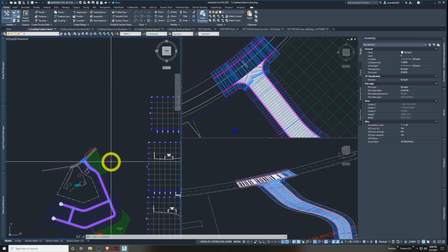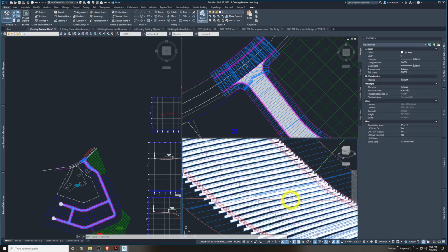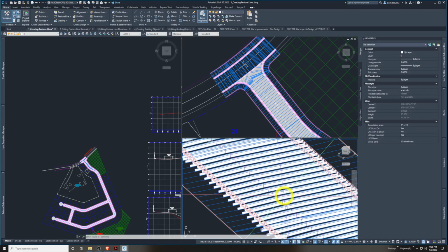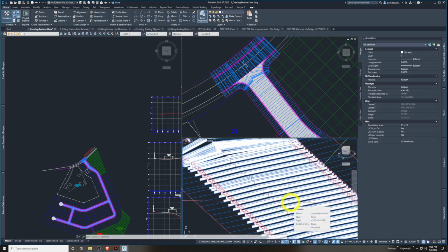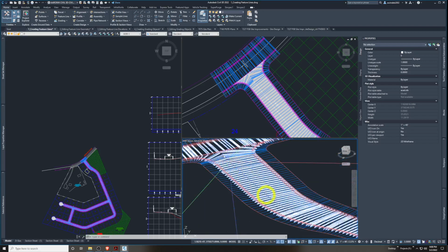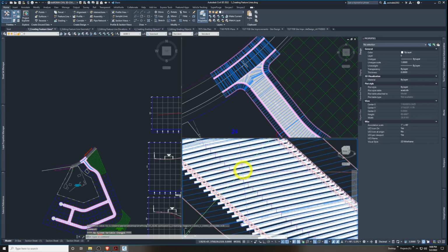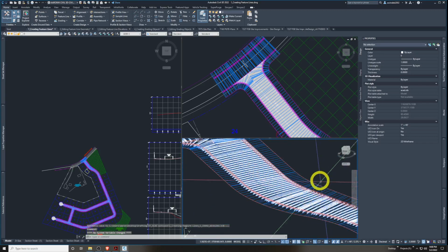Whereas when we learned earlier, and also tying back to Chapter 9 in corridors, we got cross sections and assemblies. So basically, to start over again, we had alignments, which set the horizontal more or less. We had profiles, which set the vertical more or less. And we had our assemblies, which set the cross-sectional shape all the way along our corridor and made our uniform shape of a road.